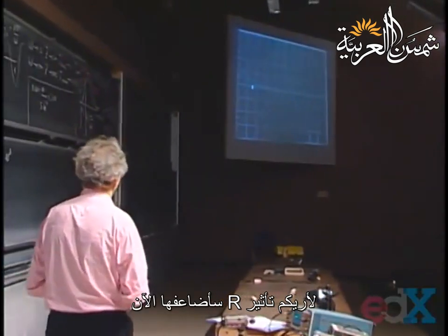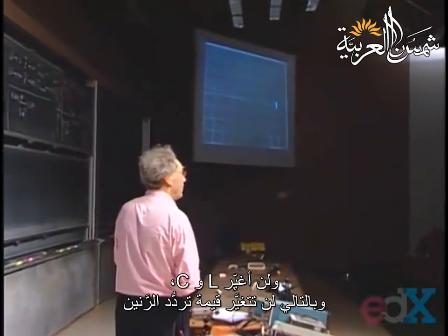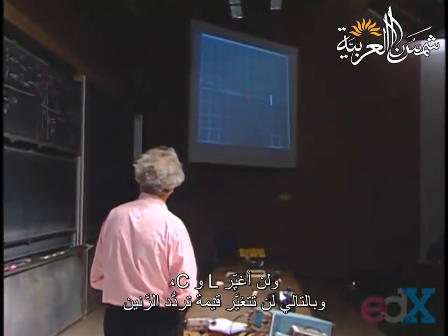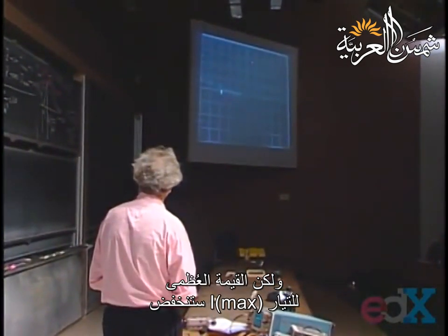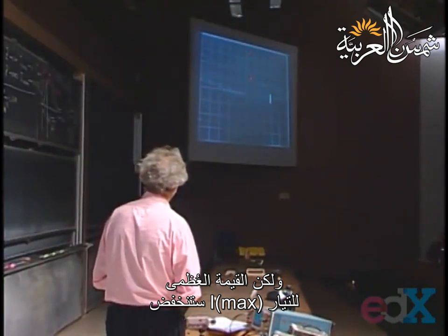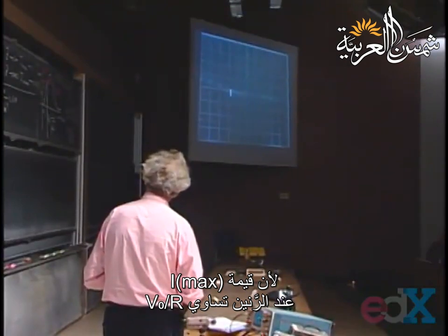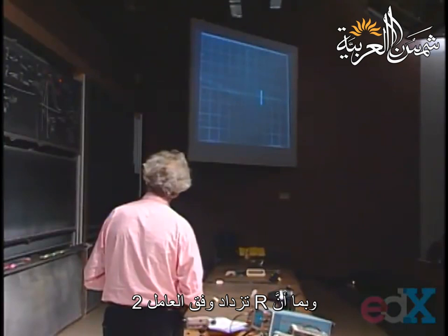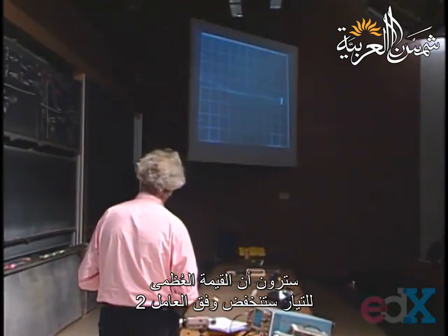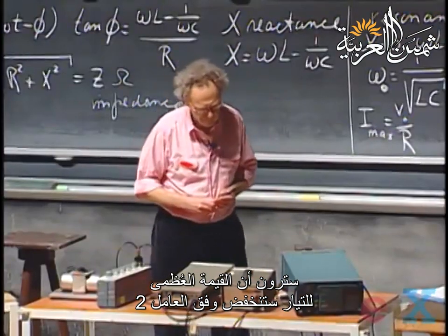To show you the effect of R, I will double R now, and I will leave everything else alone, so the resonance frequency will stay here, but of course the maximum current, this high value, will now come down. Because at resonance, this value is V0 divided by R, and since R goes up by a factor of 2, you will see that the maximum current will go down by a factor of 2.